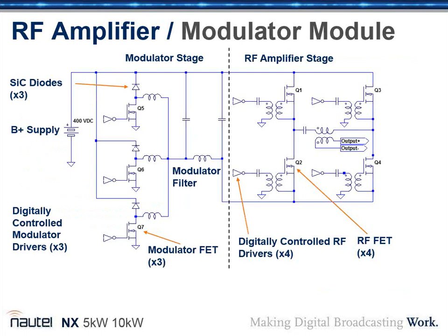So again, it helps to minimize the dissipation of the power module. So they're actually protecting the device against ringing? Is that what it is? Yeah, they allow the current to continue to flow through that first inductor after the FET is switched off.